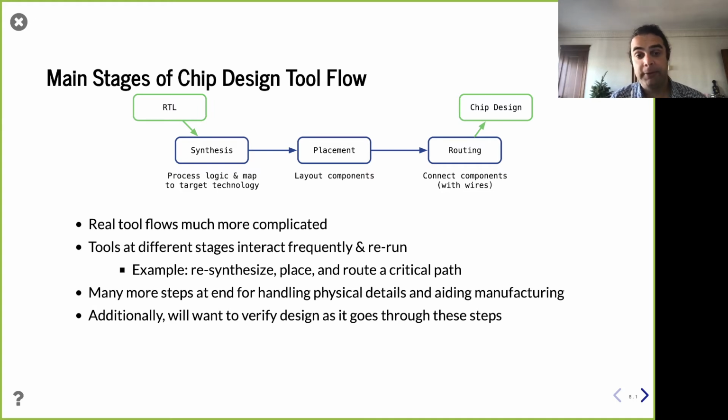Definitely, yeah. So the question was, given that these tools may have bugs, what can you do to be proactive about designing differently or putting in some sort of backdoor to help debug or prevent these bugs? It's an entire important field. There are two key phrases you might hear, DFT and DFM. DFM is design for manufacturing. That is, what considerations do you put in your design process to make it easier to manufacture?